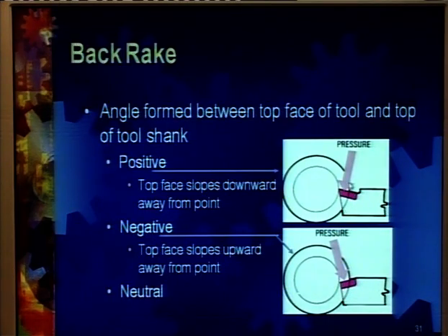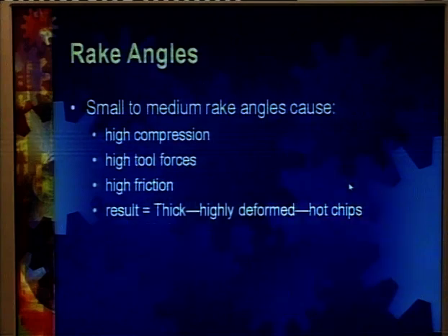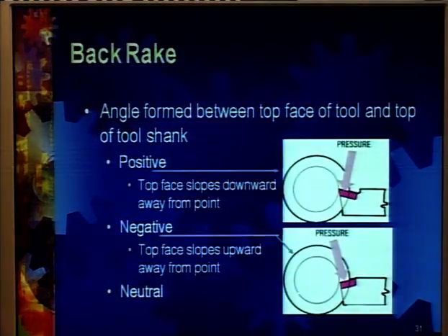We can again see, as has been written in this statement, that in case we give a positive rake angle to this type of materials, then the force which is coming onto this direction may cause the breaking away of this tool tip, in case it is made out of a material which is not that tough, just like diamond or ceramic or even the carbide tip tools.